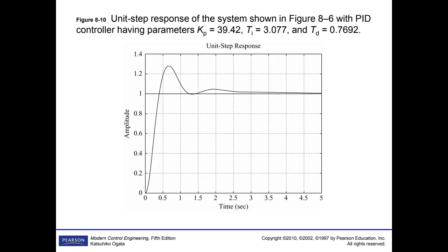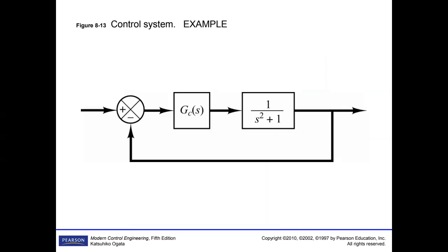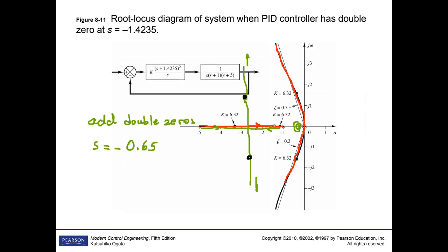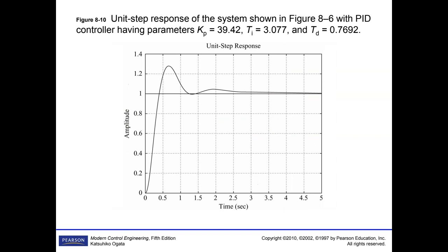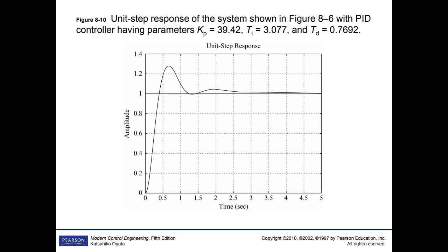This one is giving you this, and the second one, although its overshoot is slightly worse than the first one, the speed is increased even further. So that is what the second Ziegler-Nichols method and the improvement of it is all about.